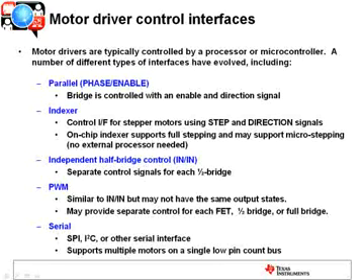You've got an indexer interface. Those are specific to steppers, which have a step and direction signal. Indexers also have on-chip indexers, which basically calculate the current and the phase to either handle the stepping, full stepping, or micro stepping. That's built into the device. There's no need from an external processor point of view to support that. It's all on-chip.